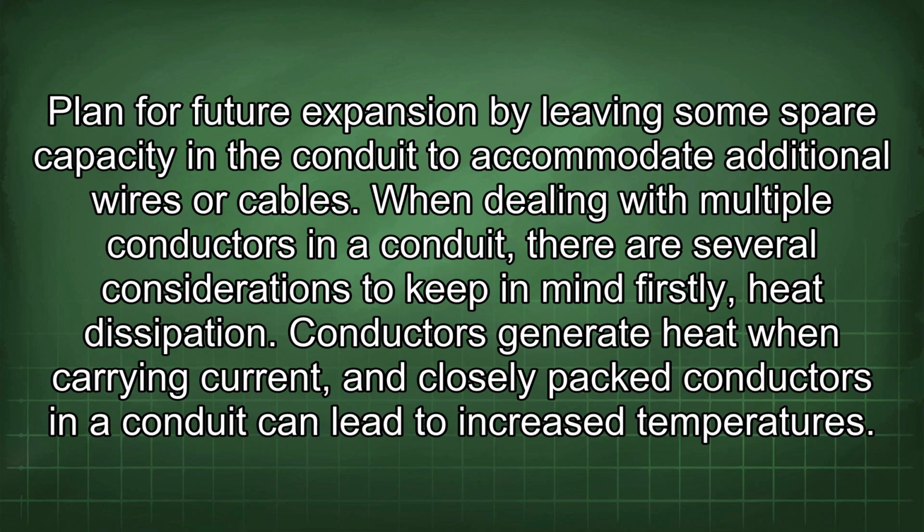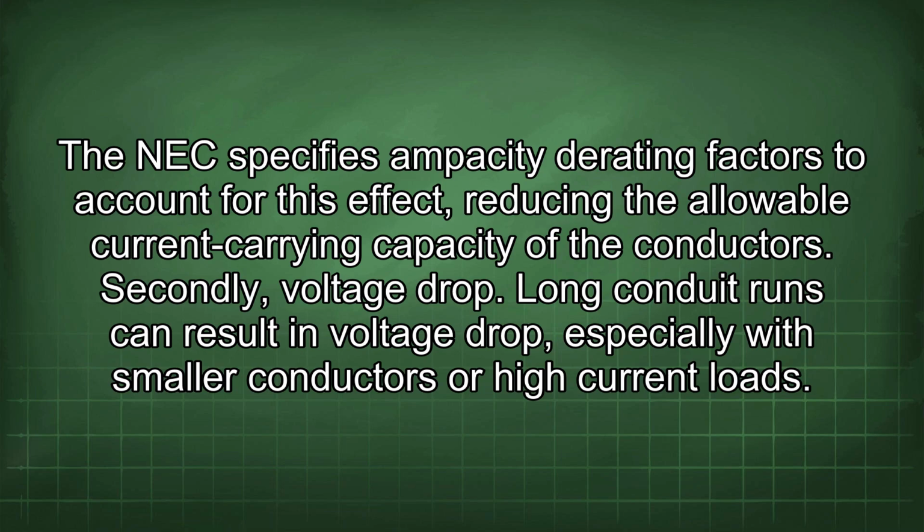Firstly, heat dissipation. Conductors generate heat when carrying current, and closely packed conductors in a conduit can lead to increased temperatures. The NEC specifies heat derating factors to account for this effect, reducing the allowable current carrying capacity of the conductors.